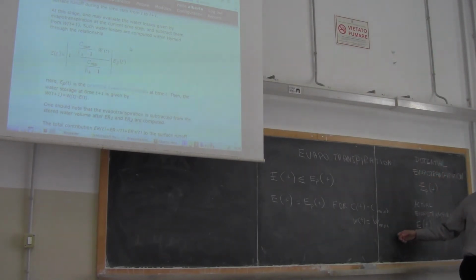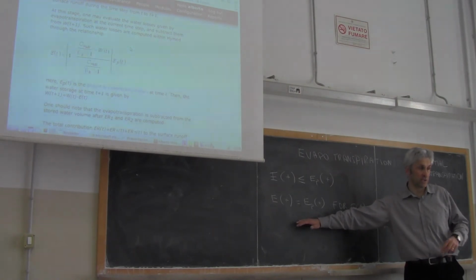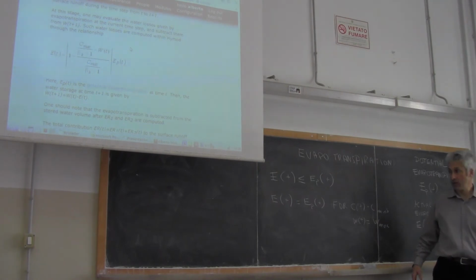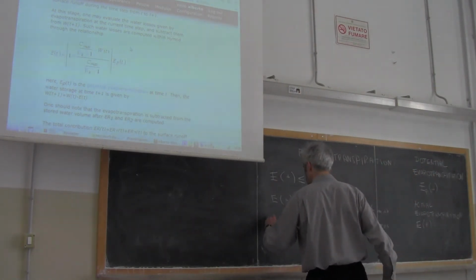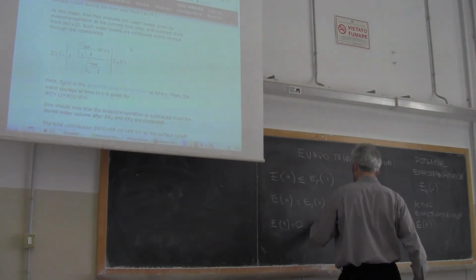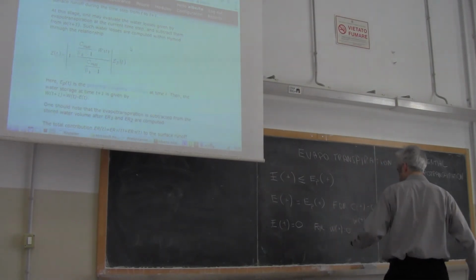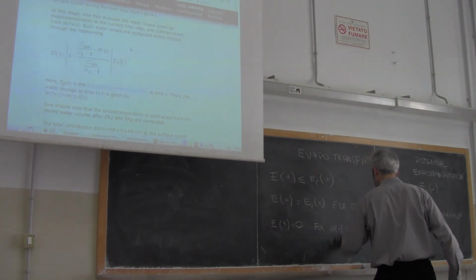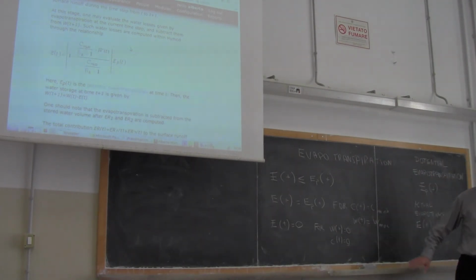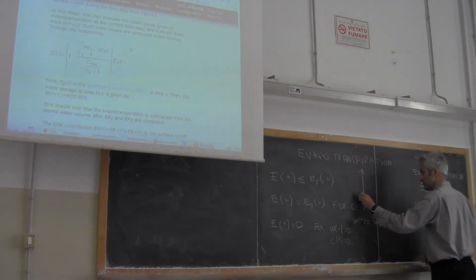When the catchment is saturated, actual evapotranspiration is equivalent to potential evapotranspiration. And also, IMOD assumes that ET is equal to 0 for Wt equal to 0, which can equivalently be written as Ct equals 0. And then there is a linear relationship in between.